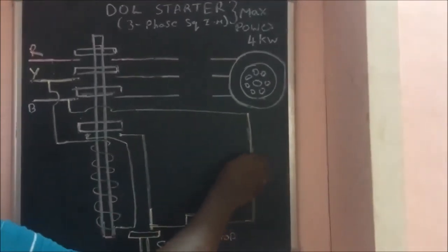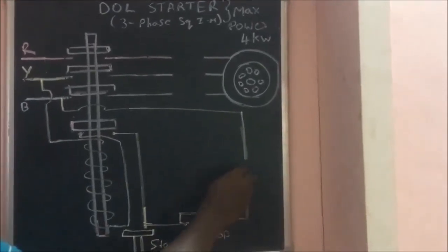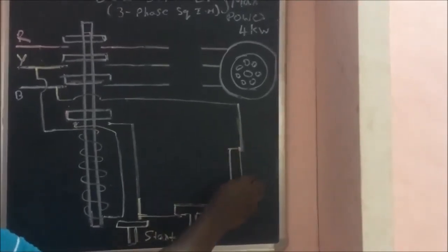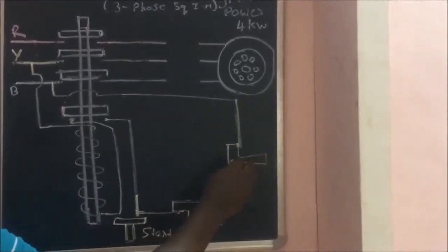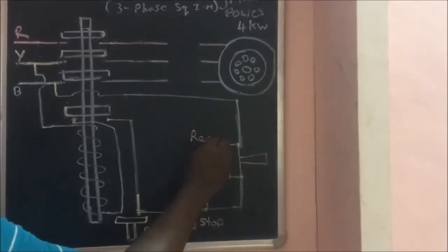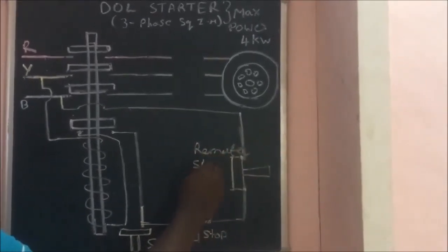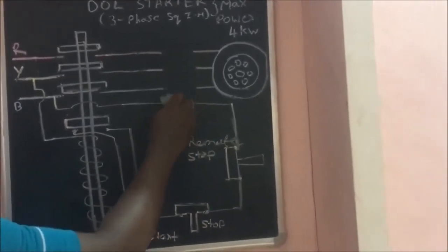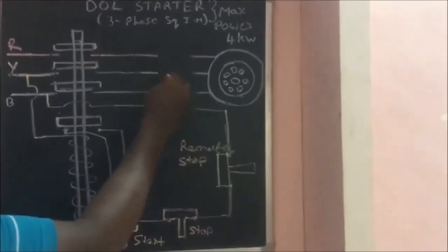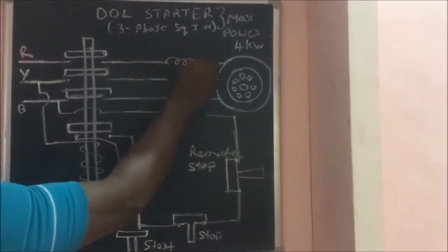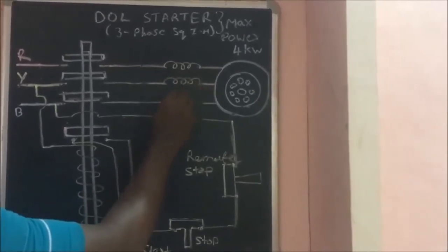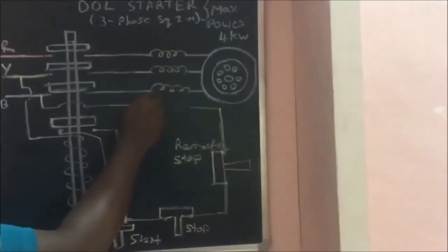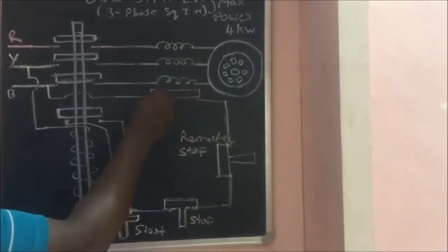Then finally the S4 switch. This is called the overload release switch. It comes below, in the right side erased region. In the erased part you have to make a winding. That winding is called the overload release coil. For each phase separately you make a winding, draw two vertical lines and connect the switch. That switch must be outward of the points.